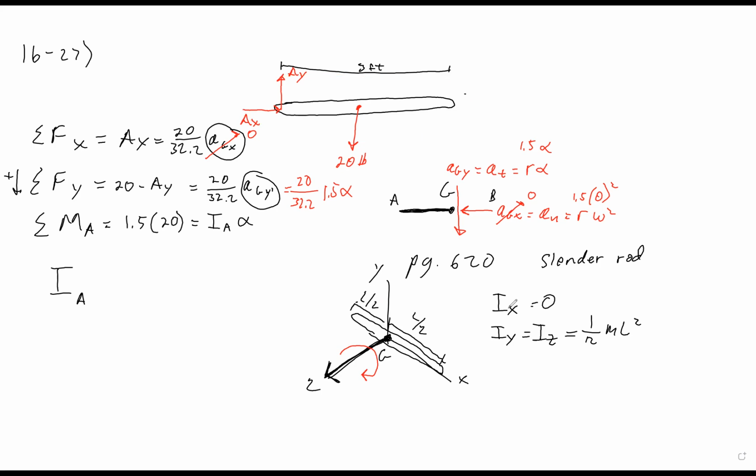Now, what about x? Why is rotational inertia about x 0? Well, that is because the rod is slender, okay? It has thickness, but we're saying that the thickness is so small that it is practically negligible. So the object rotating about the x-axis will have practically no inertia compared to whatever else is happening in the problem. This is kind of one of these things in engineering where it's the close enough moment.